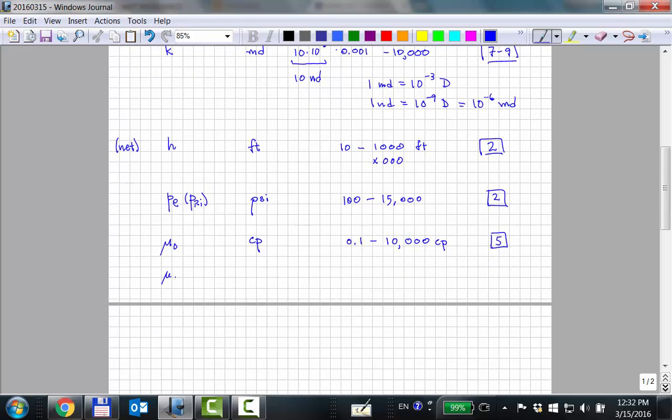Gas viscosity has a much lower range, 0.01 to 0.1. So that's 2 orders of magnitude. Right? 0.1 would be something like Kristin Field in the North Sea. It's at 900 bars. It's a rich gas. It's getting to a viscosity close to a light oil. 0.01 to 0.1.